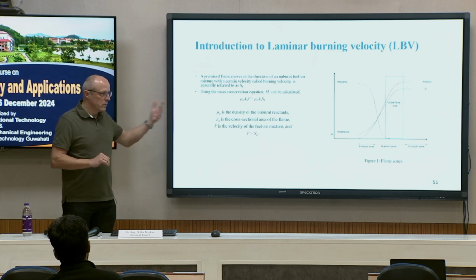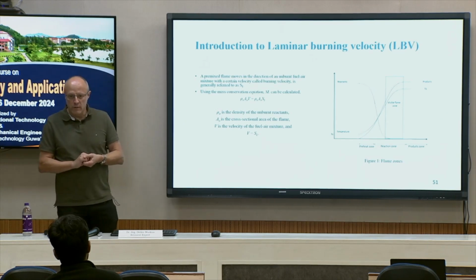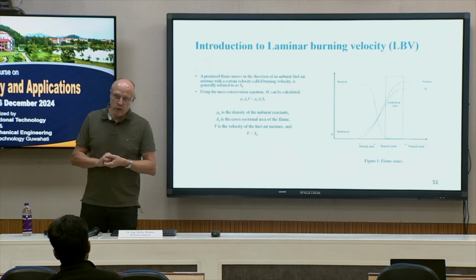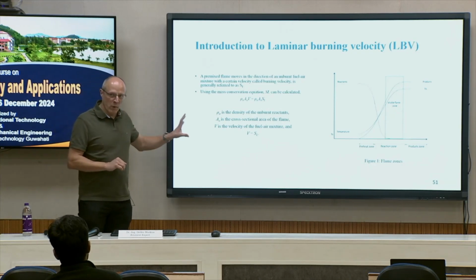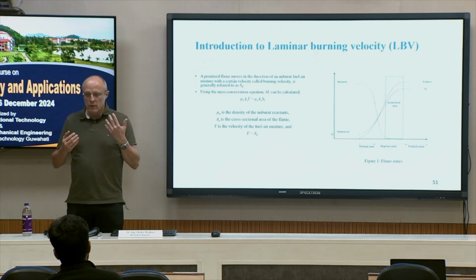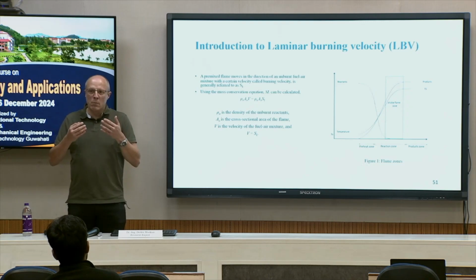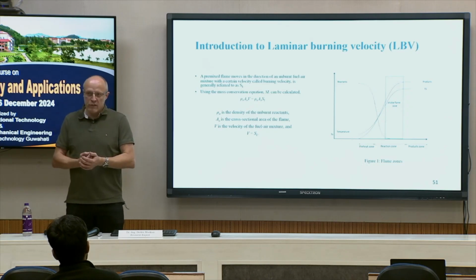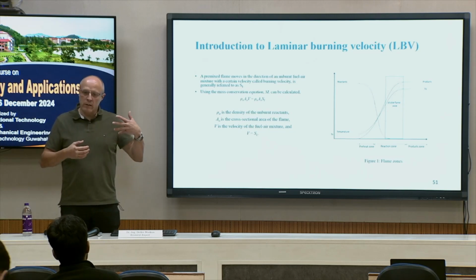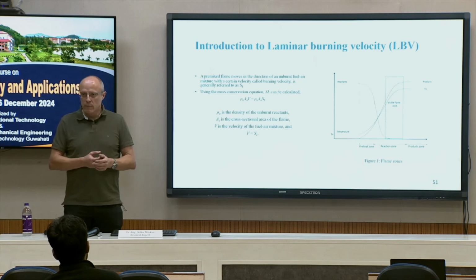Of course, most often, if you are not interested in the development of your reaction mechanism, you are not looking at such specific parameters I have presented. But very often, you just change your initial conditions, pressure, temperature, mixture composition, to find your optimum mixture configuration, which you may then use in a very complex, very expensive 2D or 3D calculation.